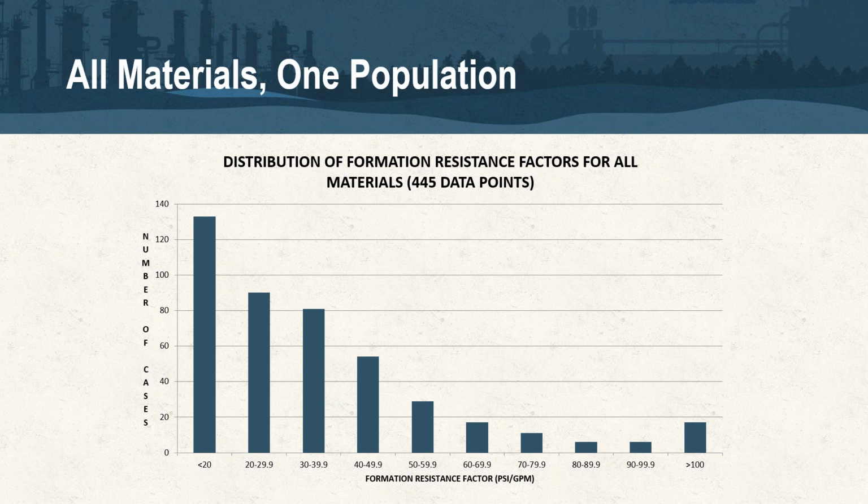And where I'm going with this is that when we do these types of injections, Derek hit it pretty hard and covered it pretty well, but I'm going to say it again: we're working with existing features and porosities within the formation itself. We're not creating new factors. We're not trying to break the rock itself and actually inject into new material. We're utilizing existing pathways and flow paths that would be both your transport zone for groundwater and, more importantly, in contaminant remediation, the contaminant itself.